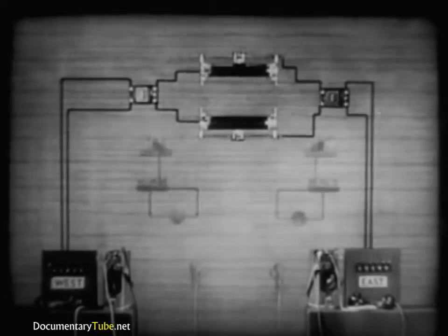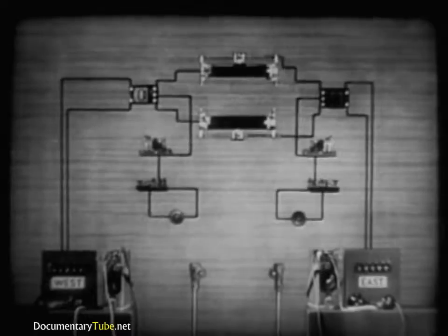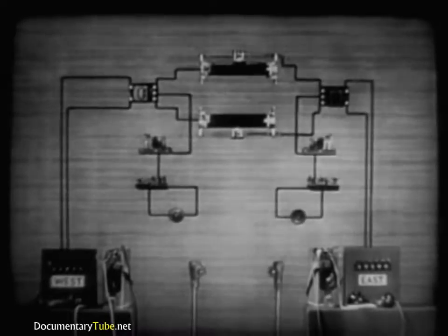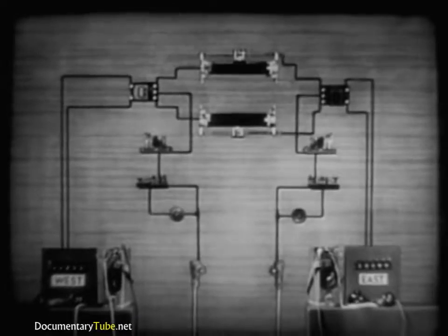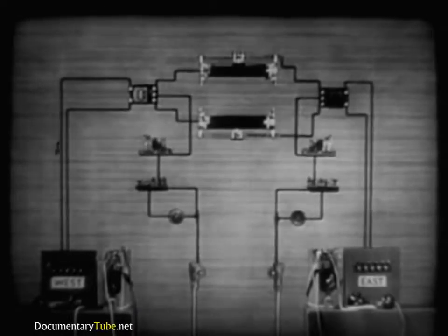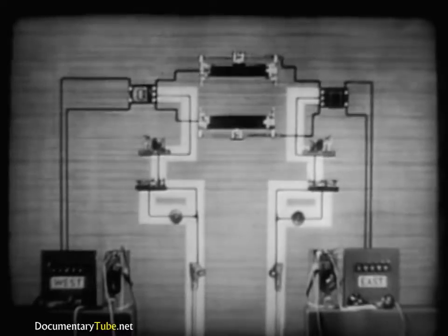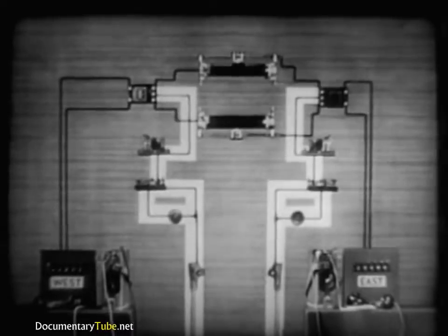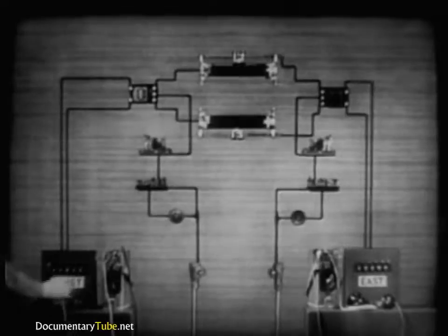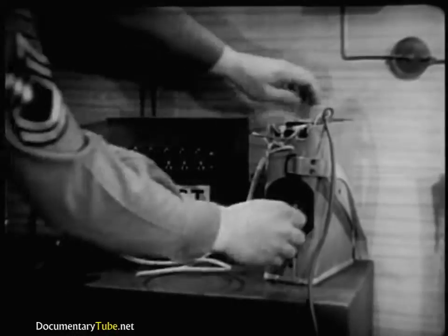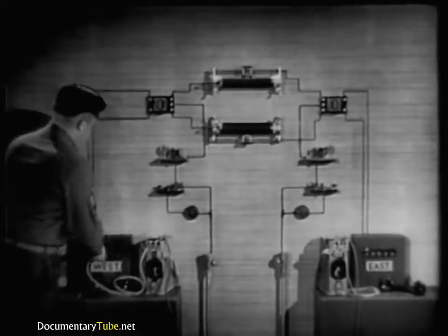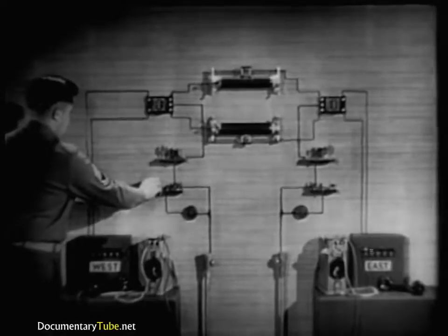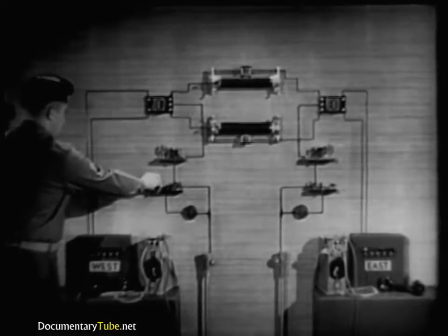Now we can connect a telegraph set to the midpoint of the line side winding of each repeating coil and complete the circuit through the earth. We have added the telegraph channel by using only a few extra feet of wire. The switchboards can still signal each other. The newly installed telegraph circuit can operate without interfering with the original telephone circuit.